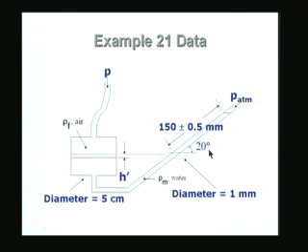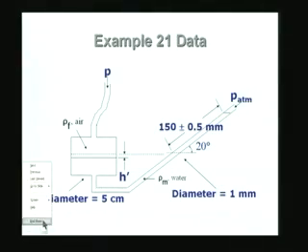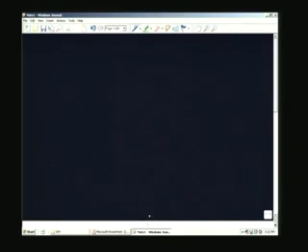If you remember, in the last lecture we said that the inclined tube is like an inclined plane, and it is a simple machine, and it is going to give you a mechanical advantage. In this case, it gives you a larger difference in the level of the meniscus, which is measured along the length of the tube. Using this, I am going to calculate a smaller height, which is what we should have measured to start with. So, we are amplifying the length by the inclined tube, and that is the mechanical advantage we can think of. So, with this basis, let us make a